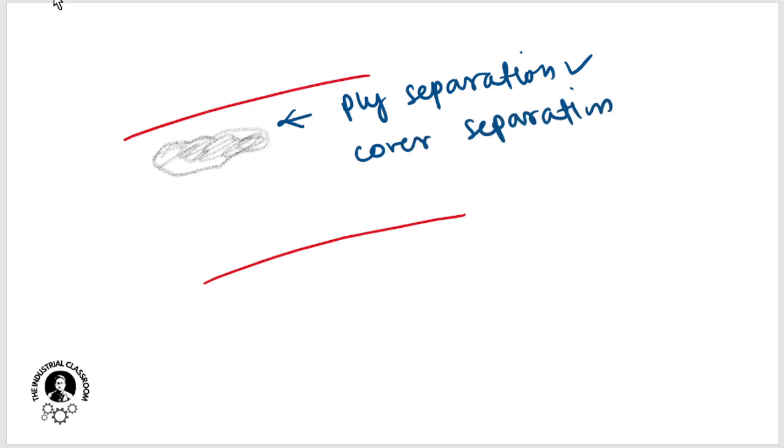And remember, this is a very dangerous issue. For the time being, what we do is puncture the bubble, or give it a small tear so that the gap does not increase. Whenever it runs over the pulleys, this air will tend to propagate, and it will create a throughout bubble, meaning a throughout separation. So in minor cases, we tear it and then repair it, but it is also not a permanent fix. We need to replace it. Except this, there is also what we can call ply separation.